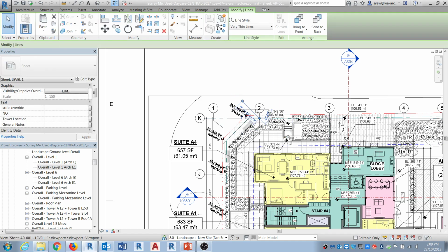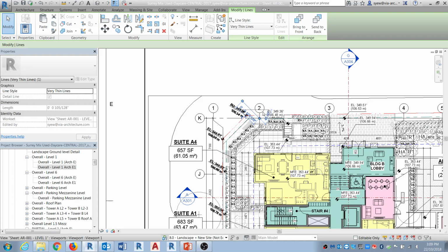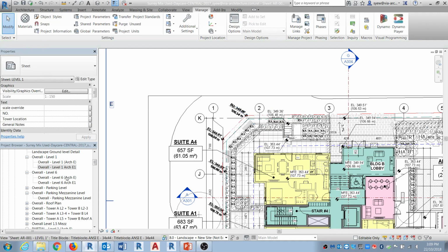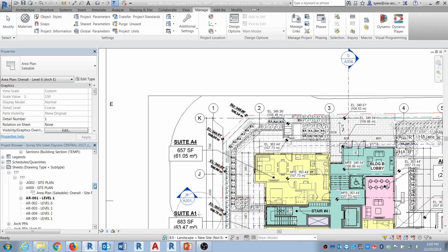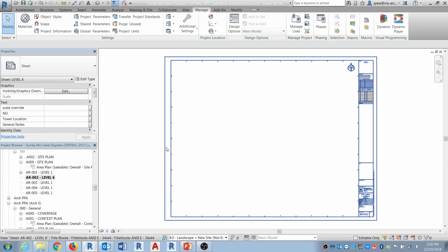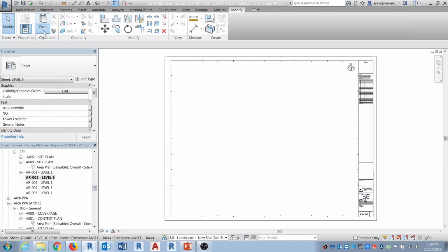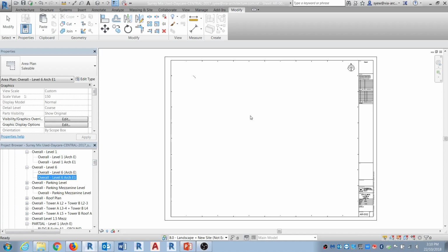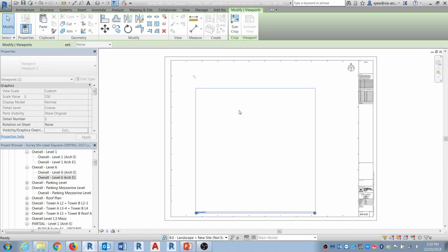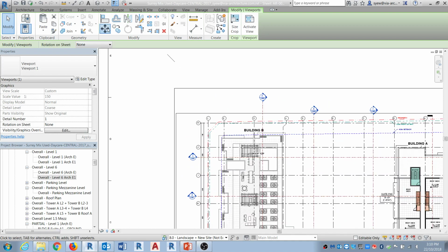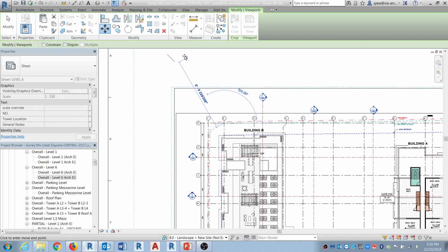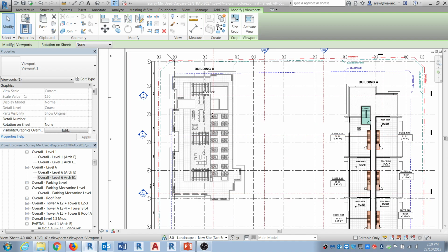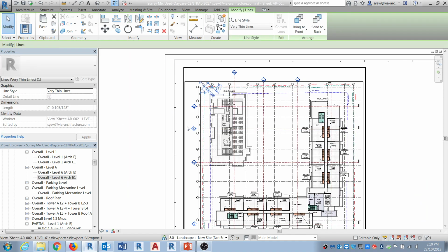What I'm going to do is use K2, just copy that, and just delete the grid. Then you go on to the next view and say place current view. The next thing you would do is just drag and drop, place it anywhere you want, and now you can just move it, and it'll snap onto that grid. Voila, very simple. I use this quite a bit.